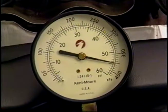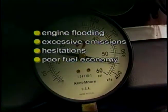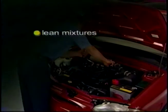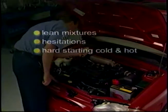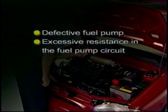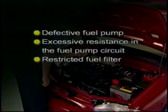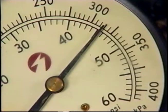Excessive fuel pressure results in a rich fuel mixture and may cause problems with engine flooding, excessive emissions, hesitations, and poor fuel economy. Low fuel pressure may cause lean mixtures, hesitations, and hard starting cold and hot. Low fuel pressure can result from a defective fuel pump, excessive resistance in the fuel pump circuit, a restricted fuel filter, or a faulty fuel pressure regulator. If the fuel pressure is within specification when cranking and running, shut the engine off and monitor the ability of the system to hold pressure.